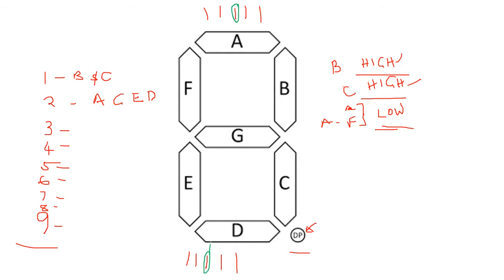matter. The only thing we make sure of is that, as usual, you use a resistor so that they don't burn. These are very, very small LEDs. Remember, because they are just LEDs, you have to protect them. You have to use a limiting resistor to limit the current from burning them. So it is important you check on that. Great. I think maybe you have now to know.